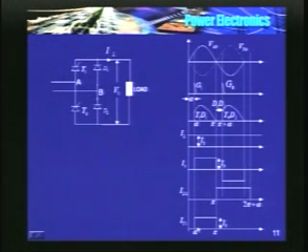So the average current rating of thyristors is less than the average current rating of the diodes, because they conduct for a shorter duration. Somehow that is not desirable. In one circuit, the average current rating of some devices is different from that of the others.